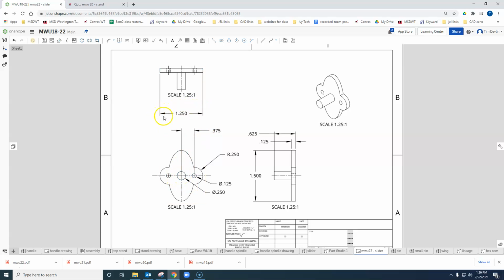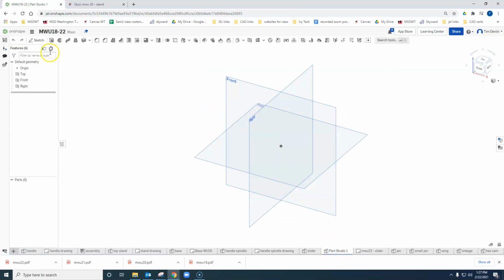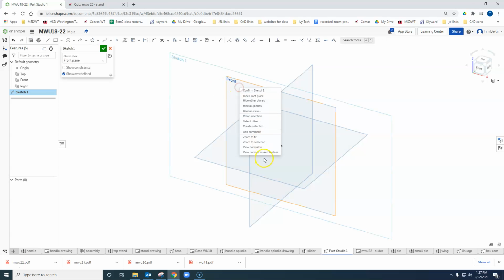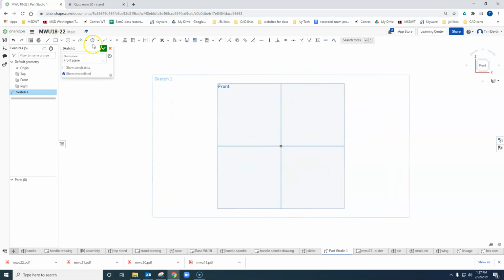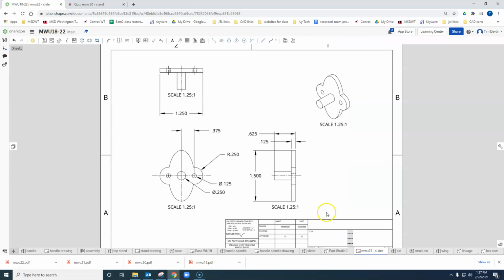And then I'm going to go 1.25 out and 1.5 tall. So I'm going to start a sketch here. And the ellipse lives behind the circle. I'm going to start here. I'm going to go up, and then I'm going to specify over. So it takes 3 clicks. And once you dimension it, you can just click it. So we want 1.5 tall, and you just click it again and move above, and it'll let us do the above dimension, which is 1.25.